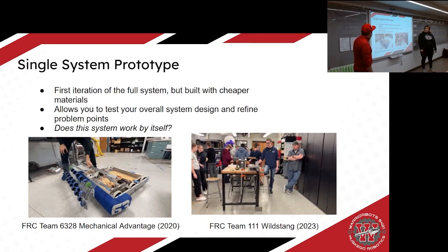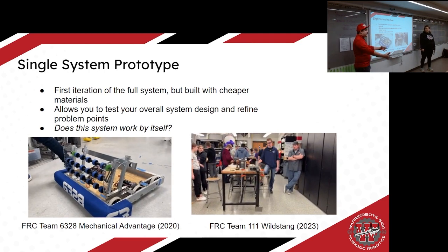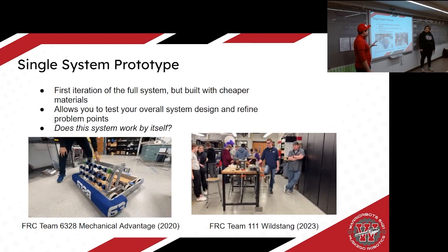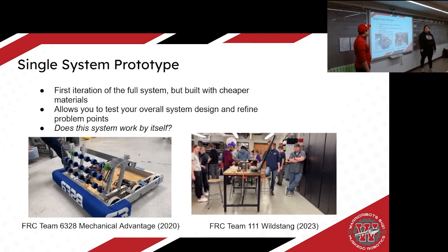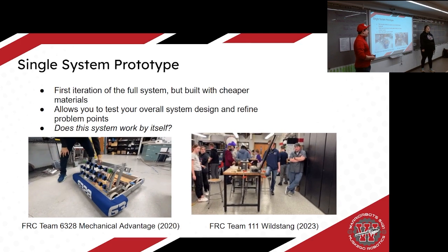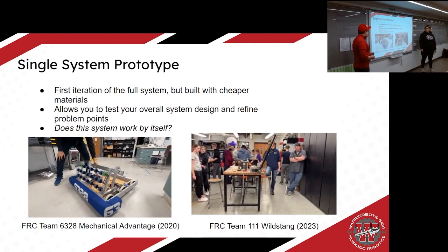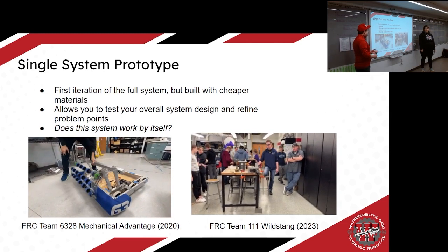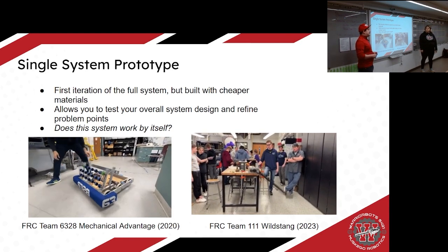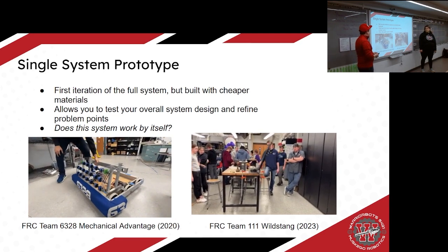Single system prototype. So this is, I've done my optimization, I know what my dimensions are, and then you build a full build of your system just on its own to see if it works. So this may not be your final iteration, but this tells you that everything that you've done is going to work. The motors are going to work. If you have pneumatics on there, that they're going to extend and retract to the right locations. It doesn't have to be out of the right materials. It could still be out of some of those cheaper materials as long as you're being somewhat high fidelity to your final product in your dimensions, at least what you think is going to work at that time.